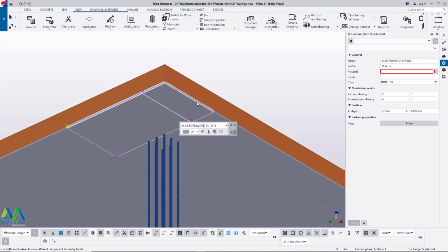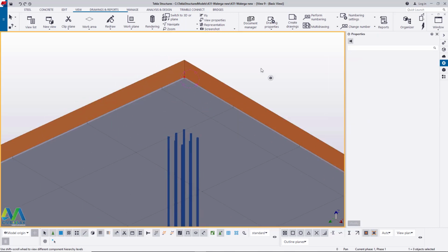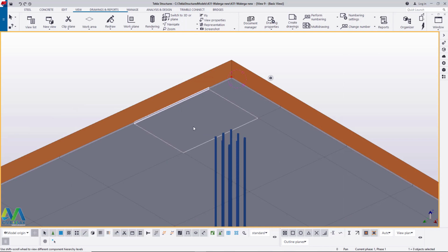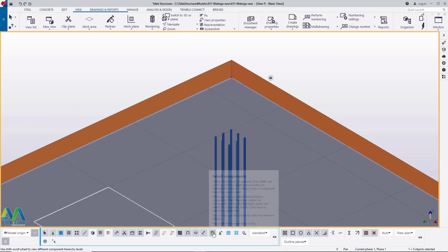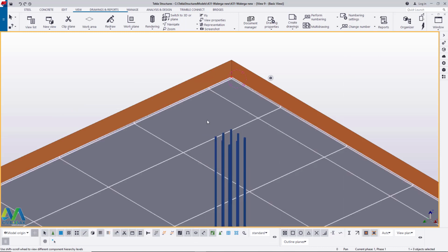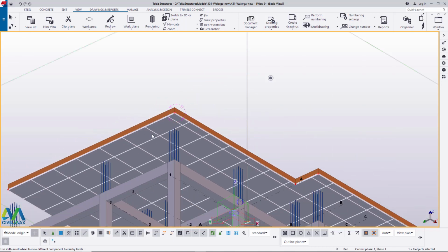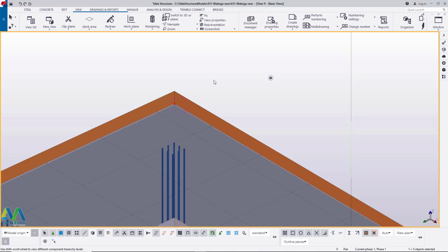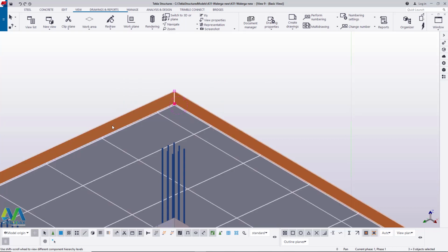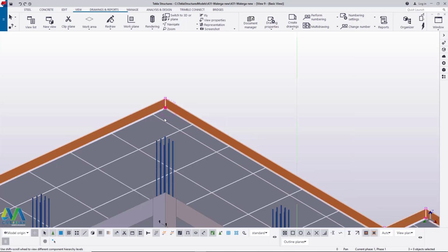Now I'll just click on empty screen, and now I don't want to select individual panels. Now I'll bring back my assembly, so when I mouse over any panel here, you'll see everything getting highlighted. Now I have to select all this so that I take it back to the 3-meter height I had before, which is the appropriate height from our finished floor level to the ceiling height.